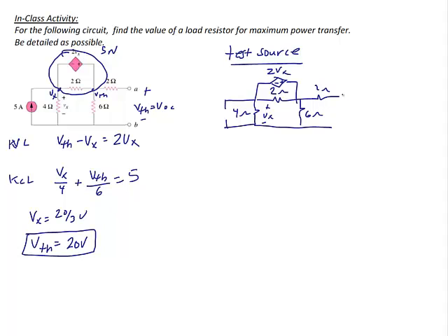And now I can put either a current source or a voltage source. How do I decide? Well, if I know I'm going to do the mesh current method, then a current source may be better because that's one less mesh where I have to do KVL. Or if I know I'm going to do the node voltage method, a voltage source may be better because that's one less node where I have to do KCL. Sometimes it just doesn't really matter. So for this one, I'm going to put I test equal to 1 amp. And what we're looking for is V test.